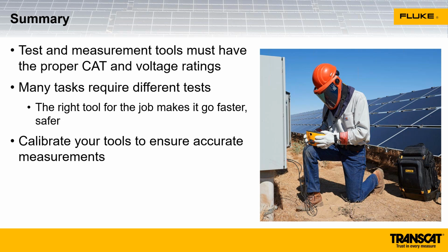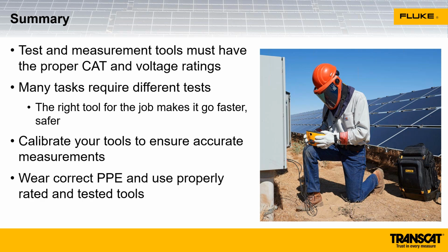Calibrating your tools, making sure they're accurate so that you're getting good measurements and taking good tests, is really important. And of course, wear the correct personal protective equipment and use it properly when you're doing testing. This technician working in a combiner box with live circuits has their electrically rated gloves, an arc flash face shield with the balaclava underneath, and their fire-resistant clothing as well.